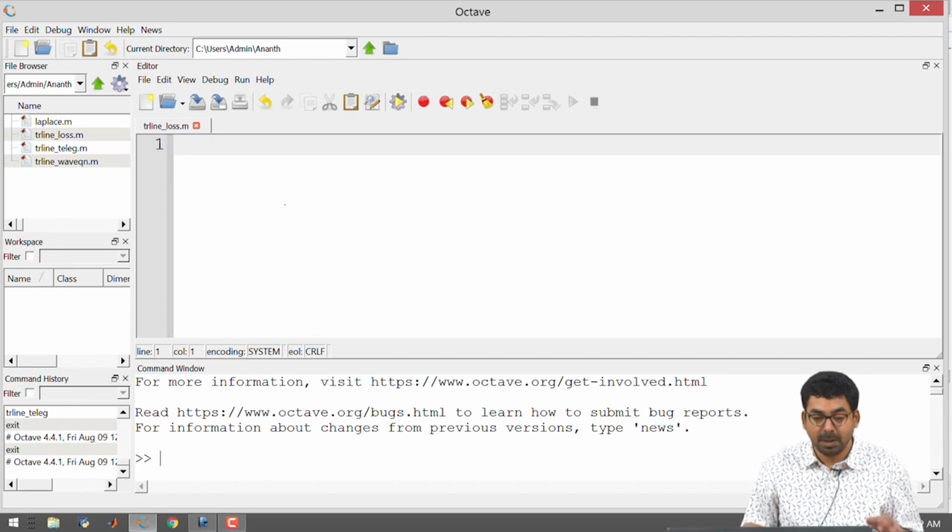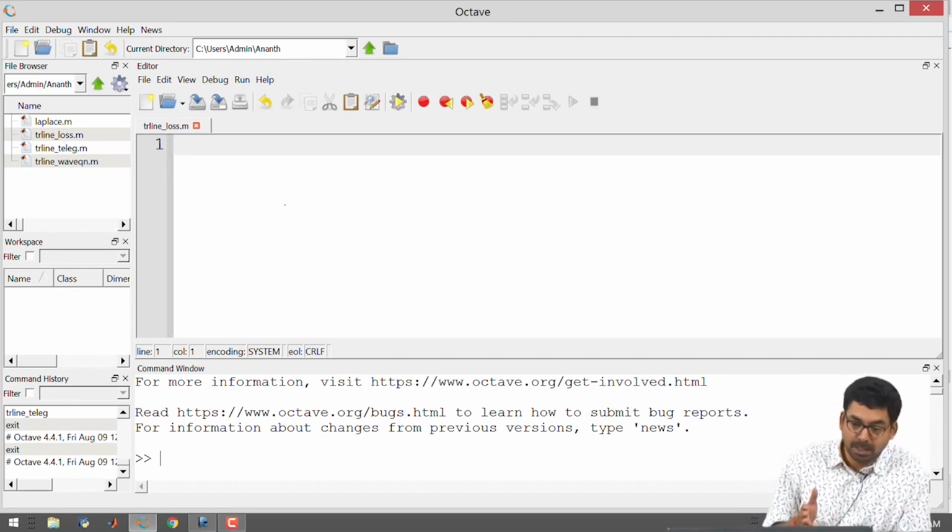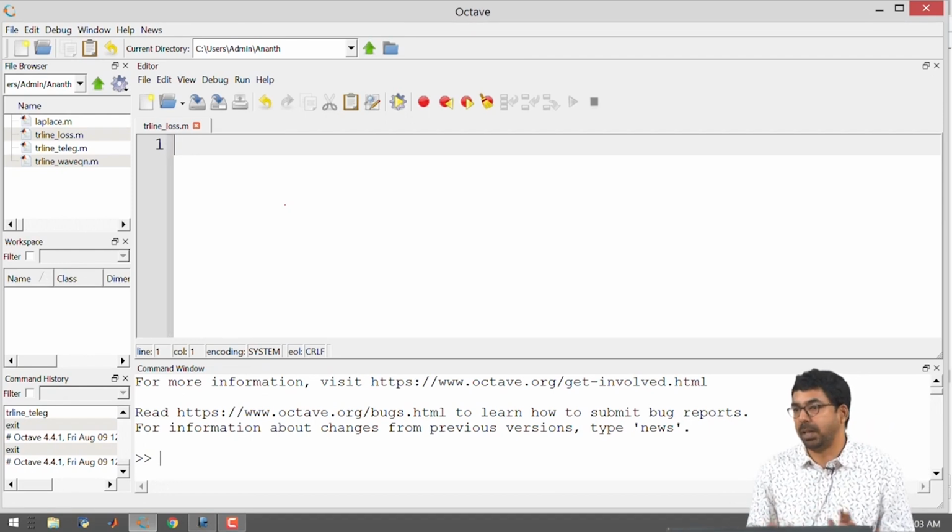So, in this class what we are going to do is see the computational, programmatic version of what we saw for the AC excitation of the transmission line, and also include the losses, that is R and G, into the model. We have derived some partial differential equations that we are going to plug into the program and actually see what can happen, to understand the exponential decay or exponential growth corresponding to your attenuation constant, whether it is positive or negative.